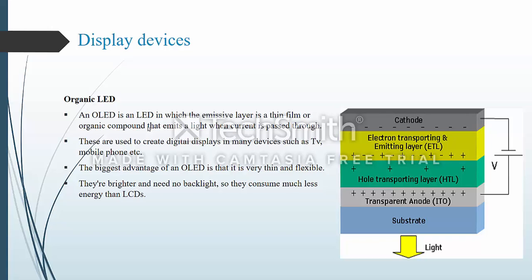To make an OLED light up, we simply supply a voltage across the anode and cathode. As the electricity starts to flow, the cathode receives electrons from the power source and the anode loses them. Now we have a situation where added electrons are making the emissive layer negatively charged, which is very similar to an n-type layer in a junction diode, while the conductive layer is becoming positively charged, similar to a p-type material.